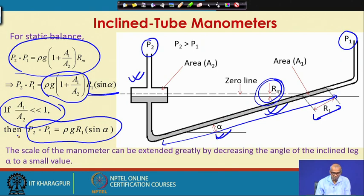The scale of the manometer can be extended greatly by decreasing the angle of the inclined leg alpha to a small value. This comes from the relationship R m equal to R 1 sin alpha. If you make alpha small, sin alpha will be small.